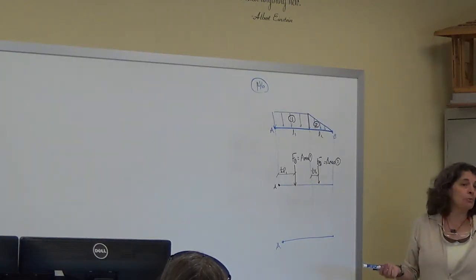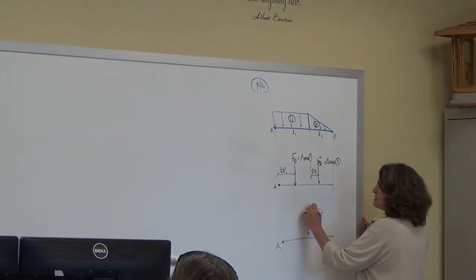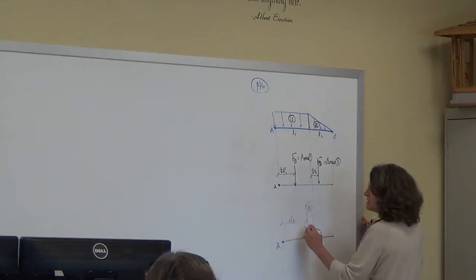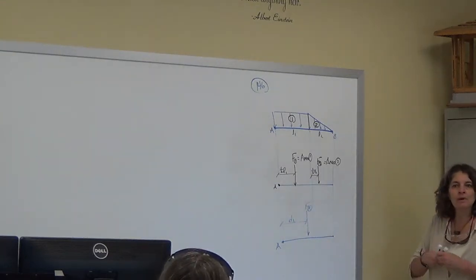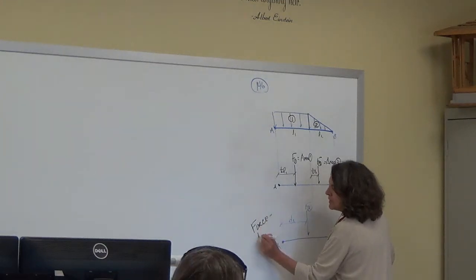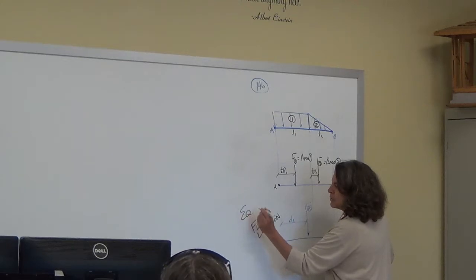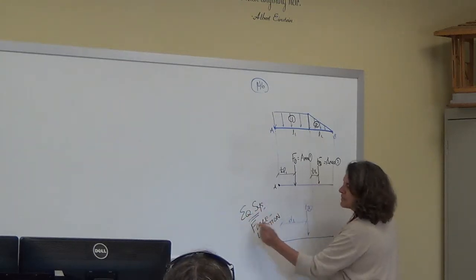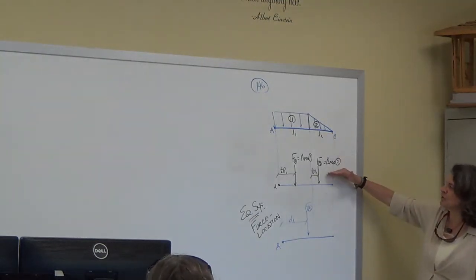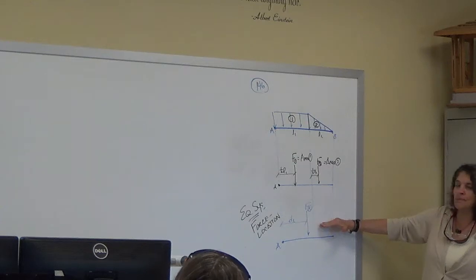It could be a force moment or a force location, but let's say I want the resultant force to be here at some perpendicular distance. What is this problem? It's a force location equivalent system problem. Right? So I took something with 2 distributed loads, I converted it to 2 point loads, and then converted it to 1 point load.